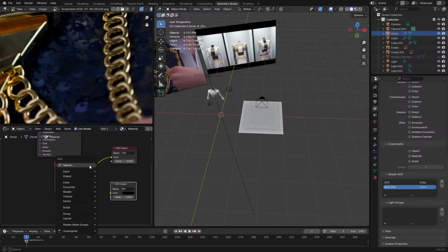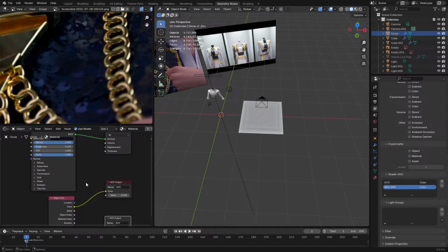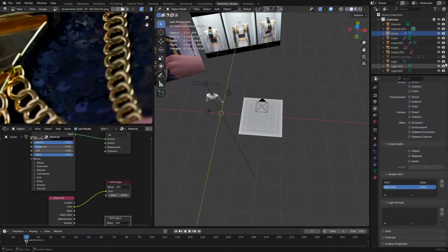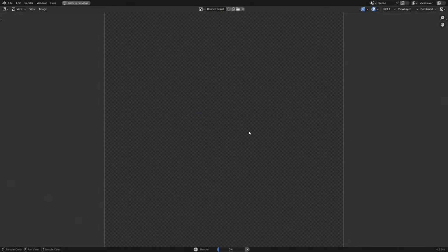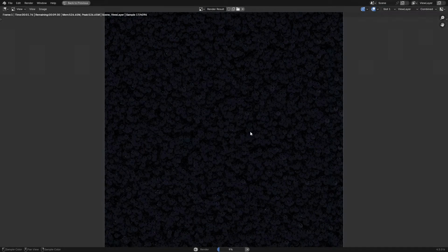And this one will be the ambient occlusion. Well, actually, no, we get that for free. Anything else that we desperately need? The random value we can convert into basically anything else. So I think that's all the information that we need. We just need the normal and the random. AO, we also have that. Okay, so with that, let's go and do a 10-second render. So time limit 10 seconds. Denoise is fine. The compositor is still on. Dang it. Oh well.